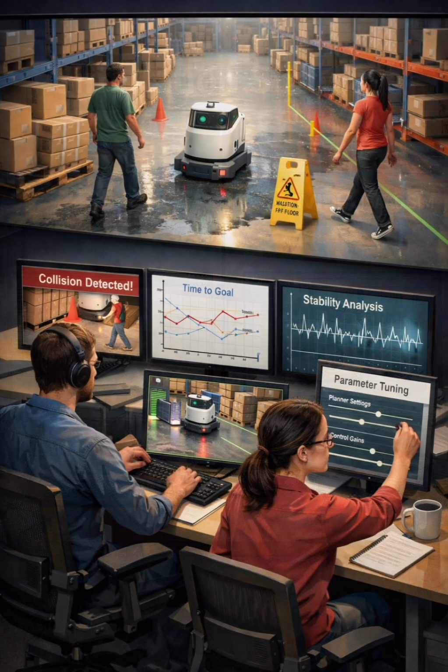Here's a concrete example. Before deploying a new obstacle avoidance algorithm for a warehouse robot, engineers run thousands of simulated runs with different aisle layouts, moving people, sensor noise, and slippery floors. They measure outcomes like collision rate, time to goal, and stability of control. If the robot clips obstacles or oscillates, they adjust planner parameters or controller gains and retest immediately, without risking damage.